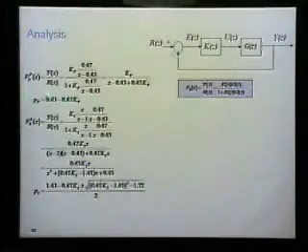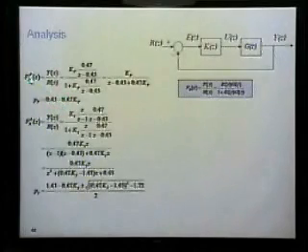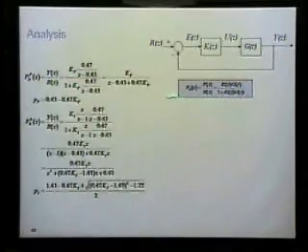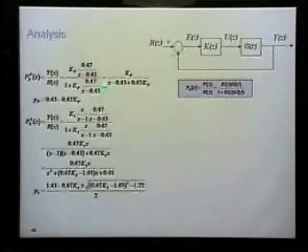Let's start with a proportional controller. What we're doing here is we know this transfer function is the ratio of the output to the input, those z transforms of the signals. We're just going to substitute in here. So k of z in the case of the proportional controller is just kp, because it's just that constant, if you remember from the slide before. That's the controller. And then we have g of z, this is our system here, that's its transfer function. And then we've got 1 plus kp times the same thing again. If you sort that out and simplify it, this is what you come up with.